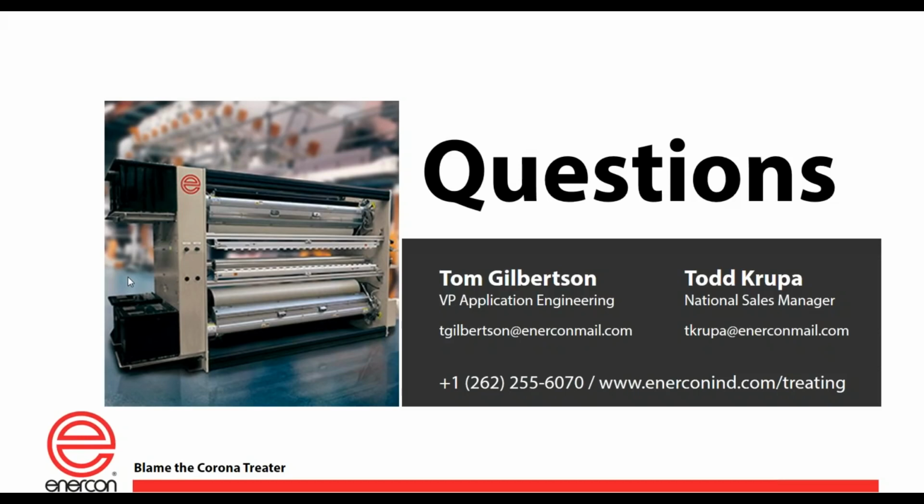A couple questions related to dyne level. Generally speaking, is there a typical rise that you see in dyne level after treatment? And what expectation of increasing watt density should we see after treating, say, at a dyne of 36 to 38? Again, it looks like trying to predict. It's really hard to predict. If I had to throw a dart at this, based on experience, if you have polyethylene film coming to the press at 38 dynes and you're running through the treater, it likely comes out of the treater at a watt density of 2. You might be in the low 40s. It might be 42, 44, something like that is pretty common.